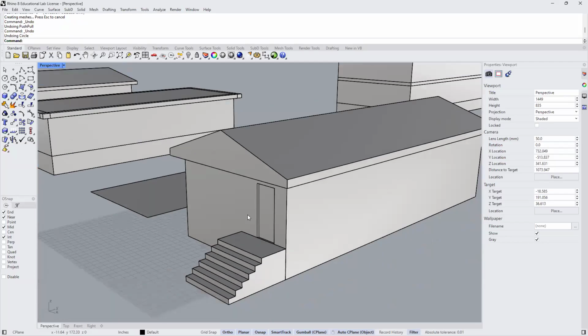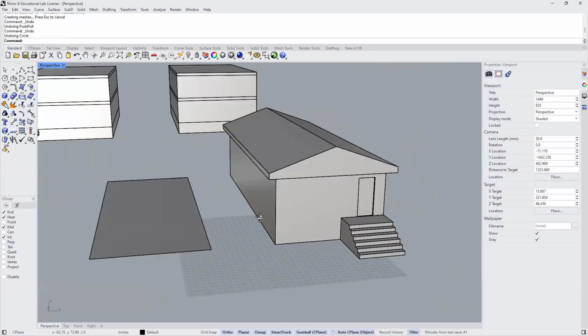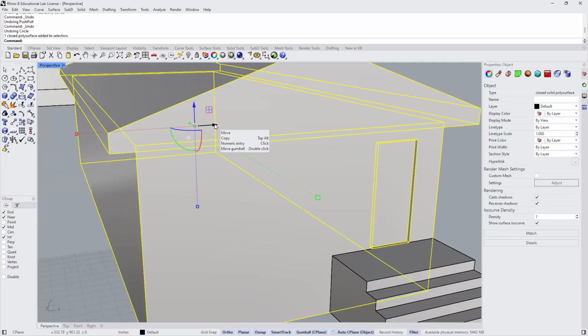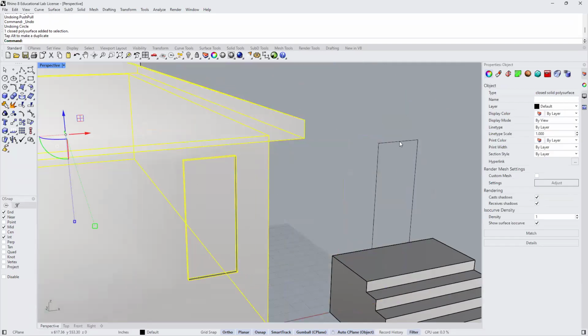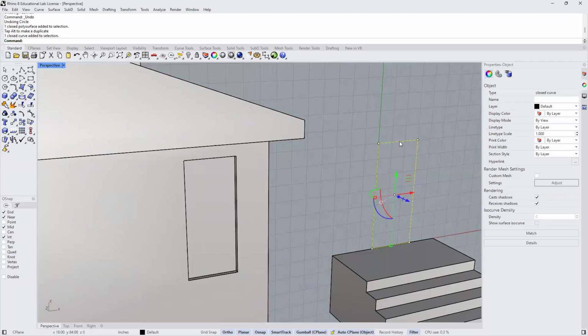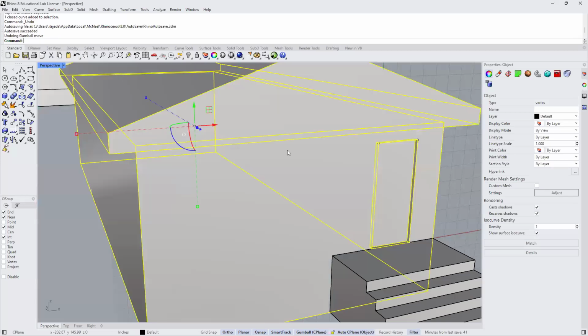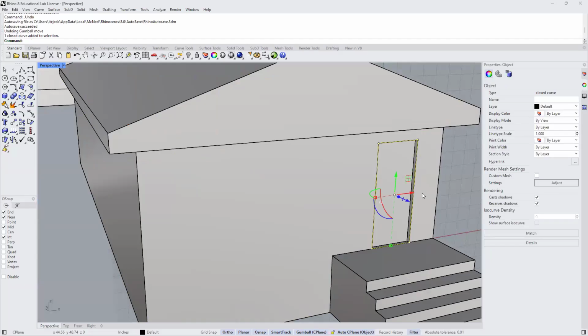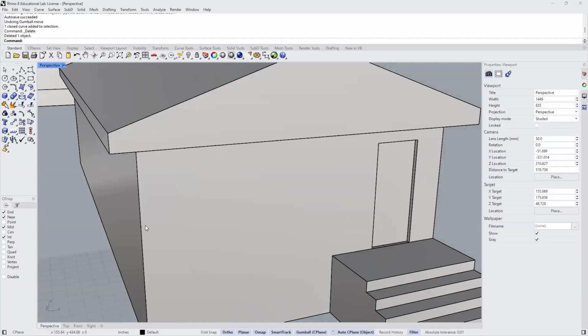So that's my door. And now I would just need to put in windows. It's up to me where I want to put the windows. Also, if I take this solid, let me just move it out of the way for a second. Notice it still left that rectangle behind, so be mindful of that. Let me undo this, and then I'll just click, let's see, hold down Control Shift. No, I'm just going to click right here. It did find the curve. I'll pick it. I can delete it, and then I'll draw another curve to represent the entry here, the rectangle there. I can draw lines.